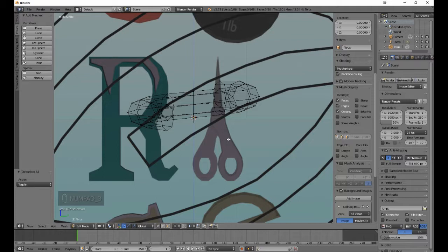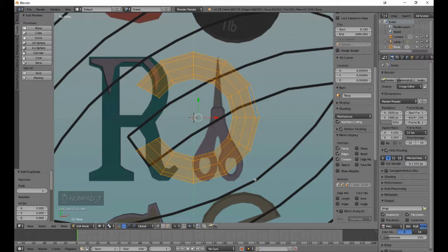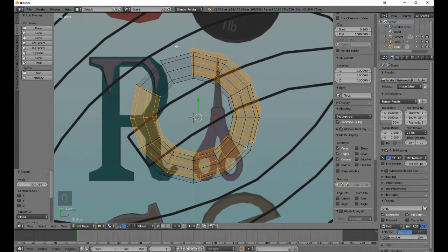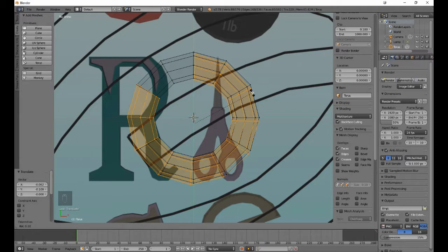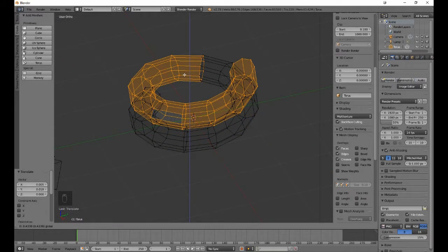or a slightly elevated one end above the other. Now if we go and duplicate it with Shift and D and rotate it, like so, try to get it where these will match up. Right here. And lift it up on the Z-axis to where they line up.